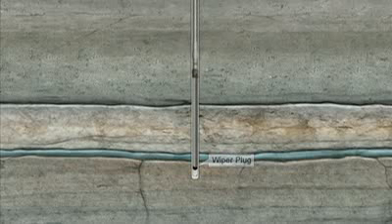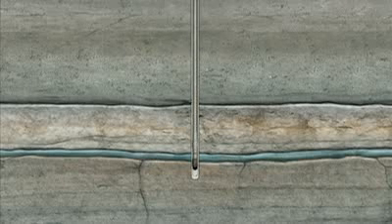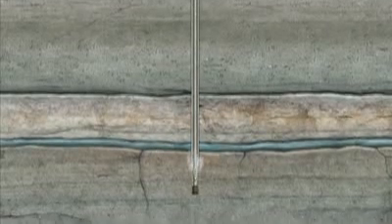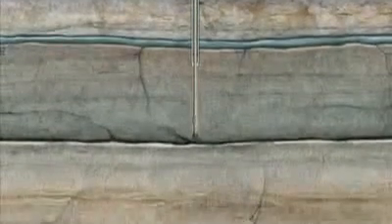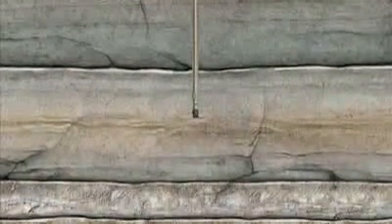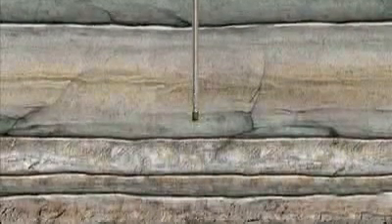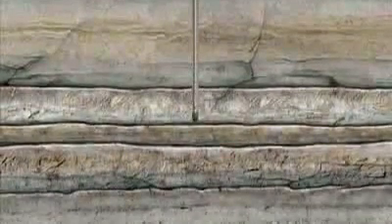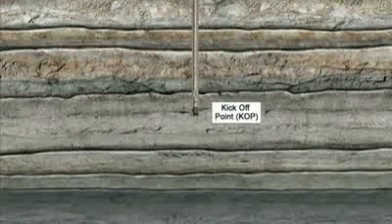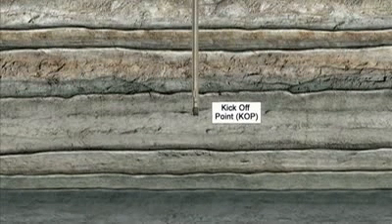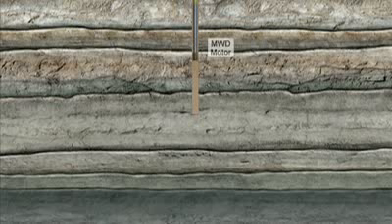rock continues. Deep below the water-bearing zones, typically 1,500 to 4,500 meters deeper, Shell hopes to find the targeted shale layers. The shale layer is often only tens of meters thick. The objective for the well is to touch the greatest surface area of shale rock, which usually requires that the well is drilled with a horizontal section. This also allows for multiple wells to be drilled from one location, reducing the number of drilling surface locations required.